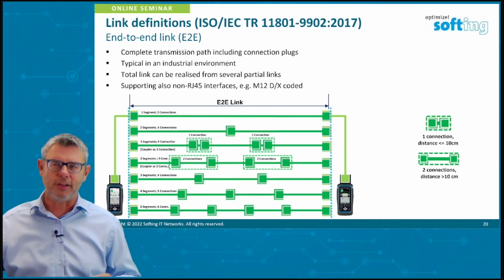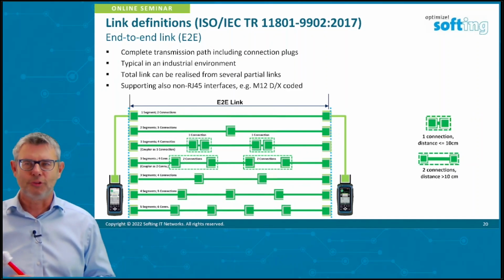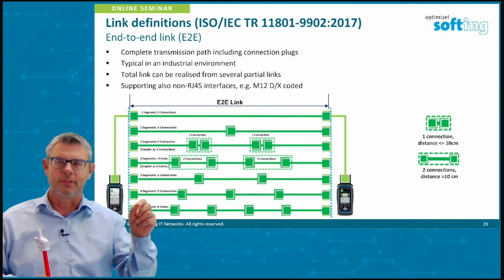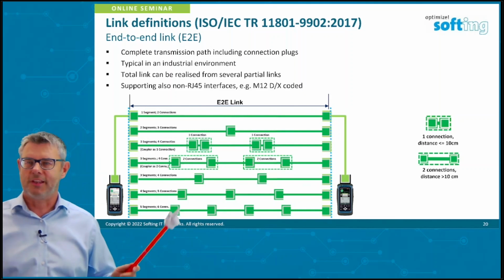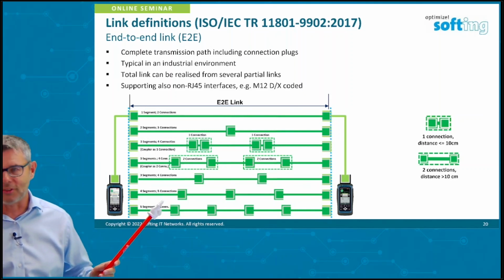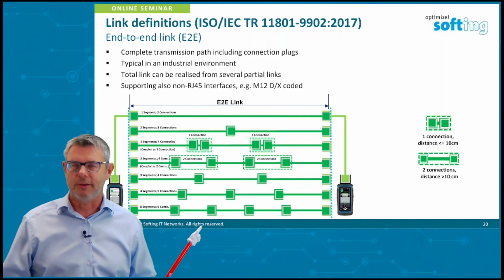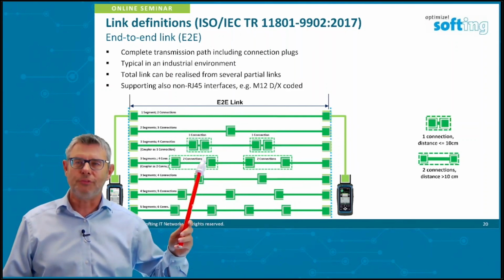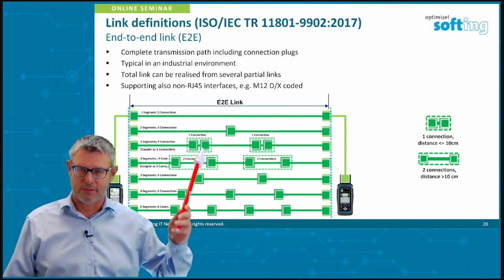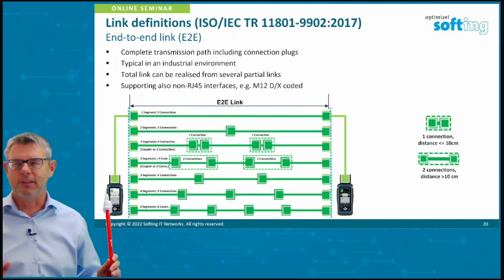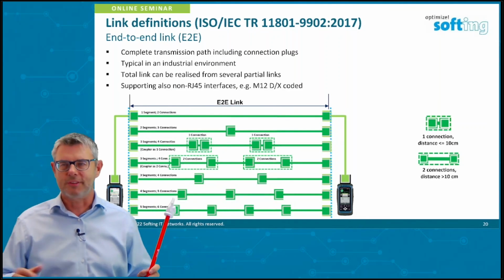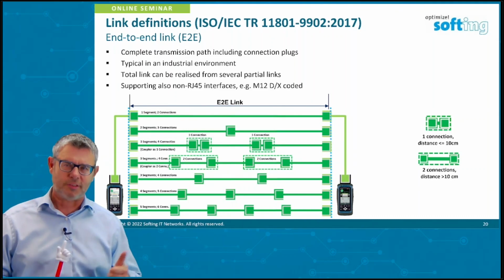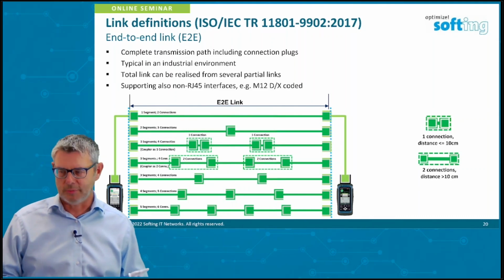You can't simply drill a hole through all the encapsulations and put your cable in. You have to make a proper back-to-back connector in the different walls of the encapsulation and so on. And this leads to this kind of topology, which allows up to 5 connectors in one of these cables. And this also has, as a consequence, different sets of limits in the standards. Okay, all these standards are programmed into the instrument, the end-to-end. So if you get in touch with an industrial environment, you are already prepared. The wire expert is prepared, first of all, with the adapters, the proper ones to use, and with the standards in the instrument itself.